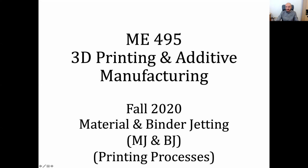This is another fundamental area. This is a fundamental additive manufacturing process. We have two versions. The first one is material jetting, and the second one is binder jetting. In the material jetting case, we are jetting the materials on the beds at very high speeds. And in the binder one, we have again a powder bed, but this time we are jetting the binders on the bed. Now we will see the fundamentals, their details, and what they have in common.